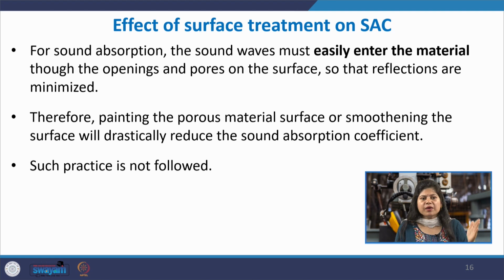Only when the sound waves are able to enter into this porous fibrous medium will they undergo all these dissipation mechanisms, and the wave energy will get lost within the material as heat. So the transmission will be reduced, and at the same time reflection will be reduced, because the waves are not reflecting back, but rather they are entering into the material.